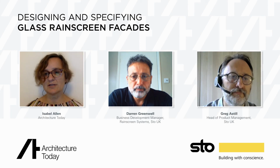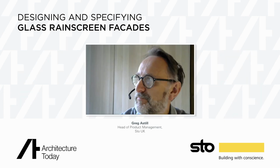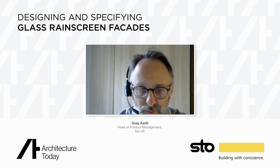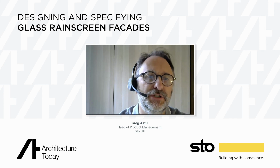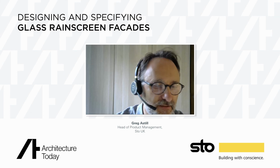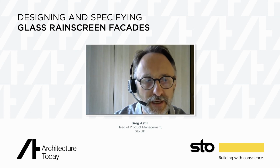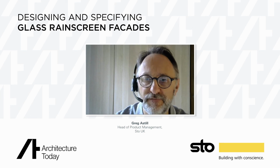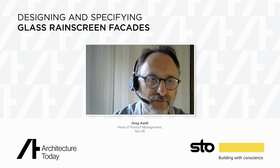Okay, Greg, can you expand on that a bit for us, please? Yes, impact is tested in line with a guideline produced by the Centre for Windows and Cladding Technology, also known as CWCT, in Technical Notes 75 and 76. That defines a range of tests with different impactors into the glass at different levels of energy.